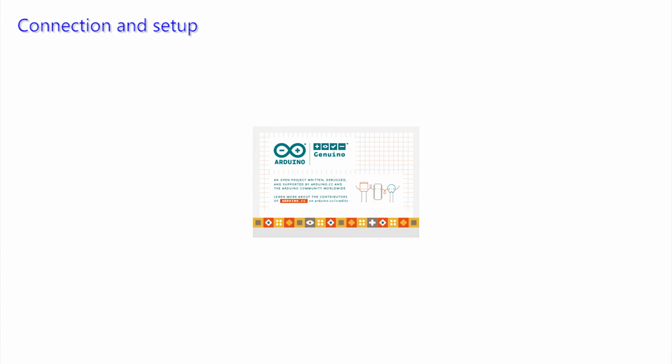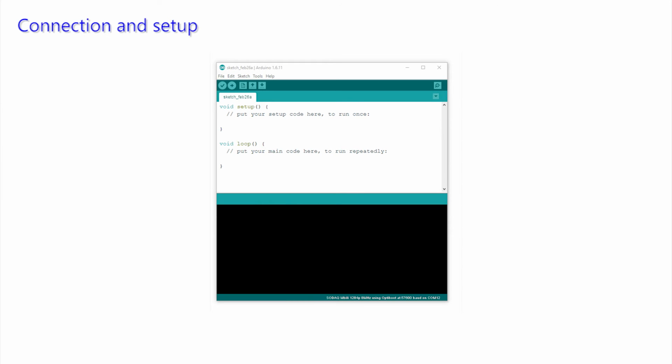It appears like this. Full details as to how this IDE operates are provided elsewhere, but a brief introduction would be that the code, which is similar to C and called a sketch, is entered into this white screen area, the text editor, and may be checked by pressing this tick button in the toolbar, or checked and uploaded onto the Mbili board by pressing this arrow button. The results from both of these operations are reported down here in this black message area.